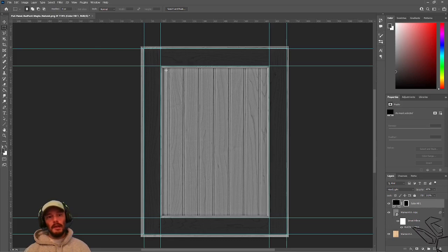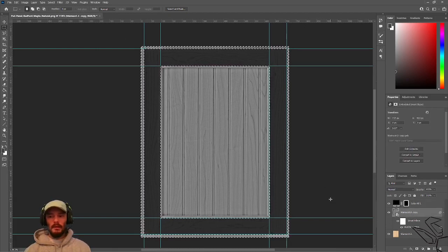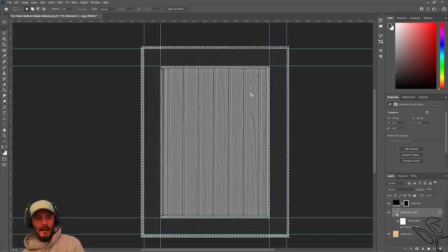One thing I might do is I might invert that selection, or in this case, we can hit my Control key. You can see our cursor changed at the bottom corner here, and select the mask. And now I can Control Shift I, invert the selection. Now I'm getting the other parts of this, and I can go back to my layer underneath here, kind of pull out the black channel, because we have black as height.